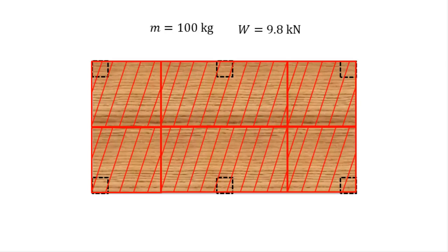Of course, once you found the area, you need to calculate the load by calculating the volume of that area, and then multiplying that volume with density to get mass, and then multiplying that mass with gravity to get weight.